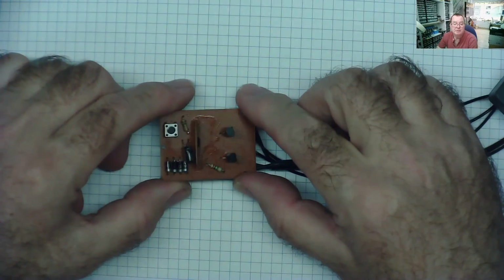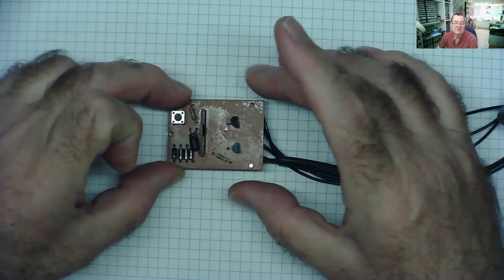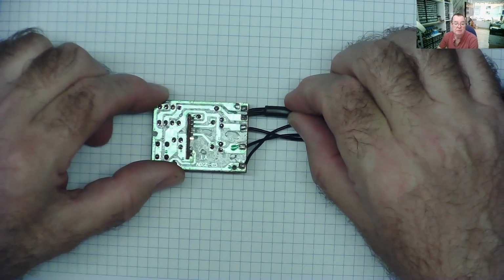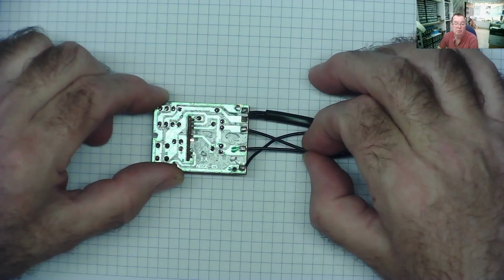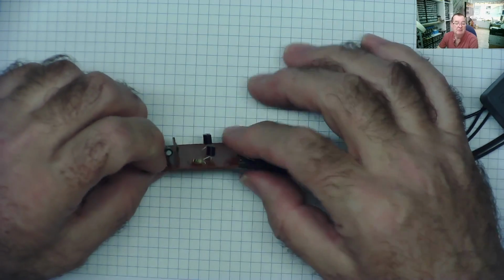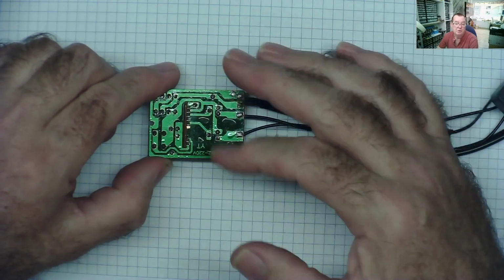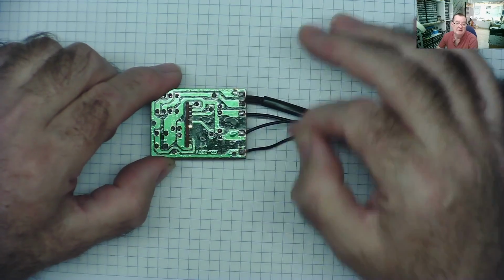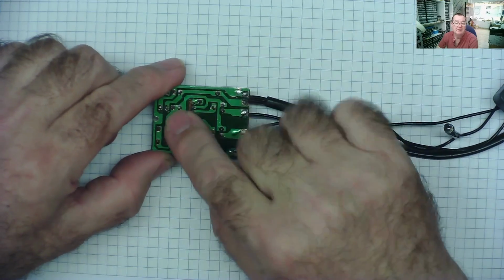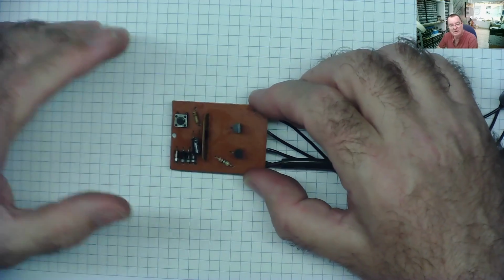The way this type of circuit works then, because this is the other type of implementation you'll find thyristors. In this case, the whole circuit is at mains voltage. This is your mains coming in, live and neutral. You'll see that these two are your load. In this case, it switches two loads, this one or this one. There are two thyristors, they can switch individually. And this, if you like, is your return from your load, which also happens to be the positive end of the LED. The other end of the thyristors, if you look, comes to here, and this is hot ground. So I can basically draw this circuit how it is, and this is the other implementation.